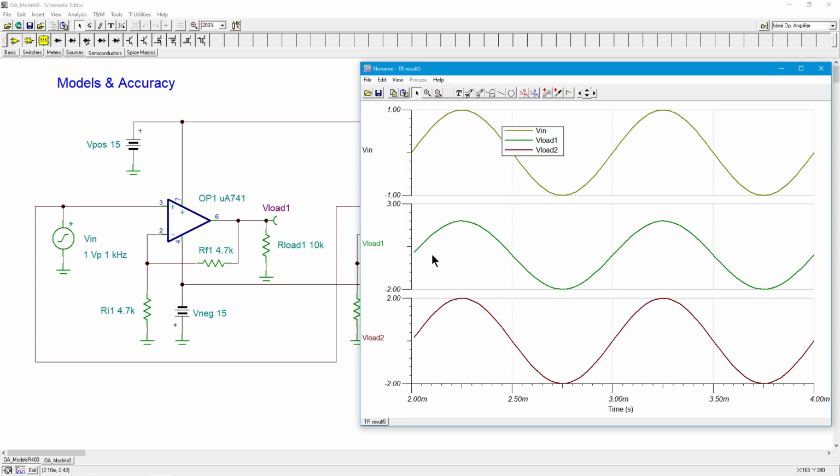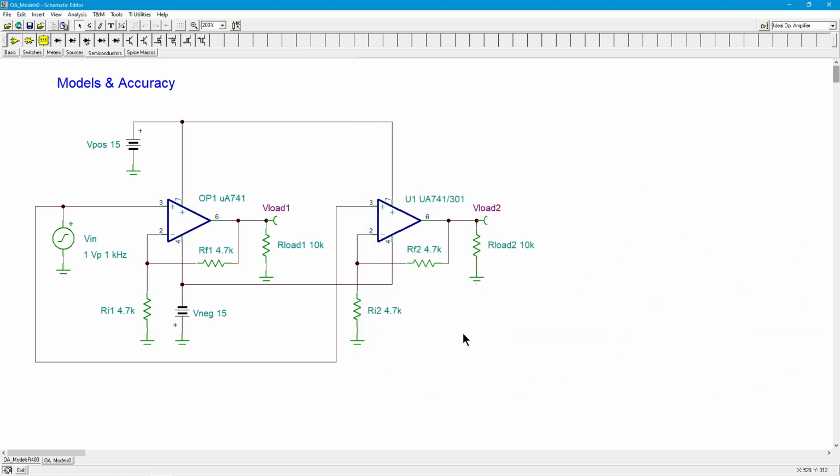All right, so here's your VN. Here's your 2 VLOADs, right? This VLOAD is scaled slightly off, probably because there's a small DC offset here, but basically it is going up to the 2 volts, okay? Let's just offset a little bit because it's going from -2 to +3 rather than -2 to +2, I'll get that right. All right, so that part so far is good. At least at 1 kilohertz for this signal, everything looks fine. I don't have any difference between these two.